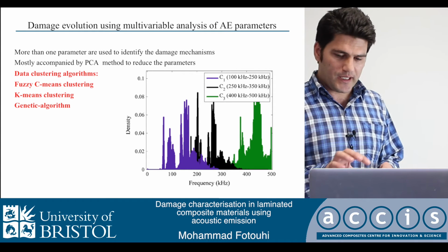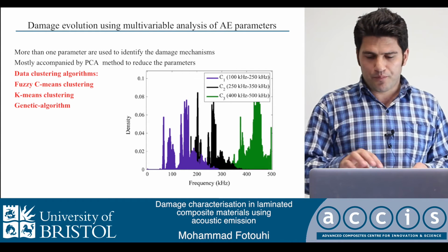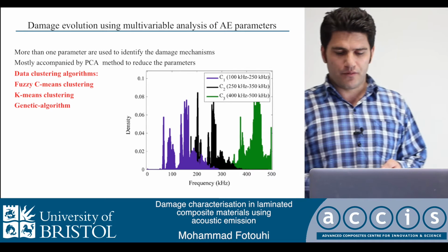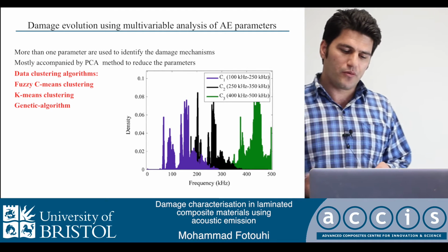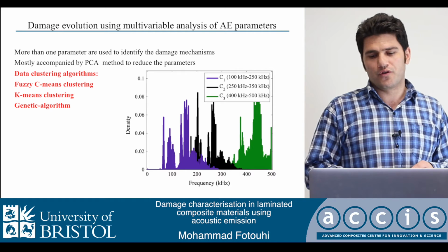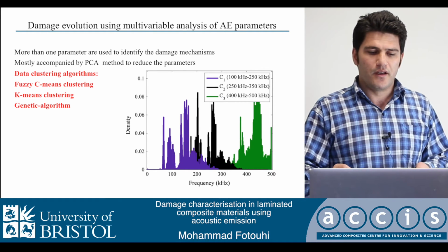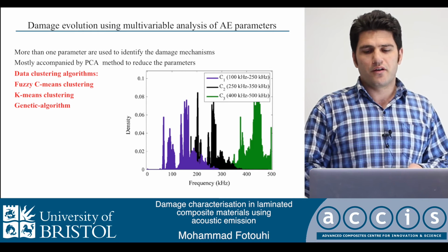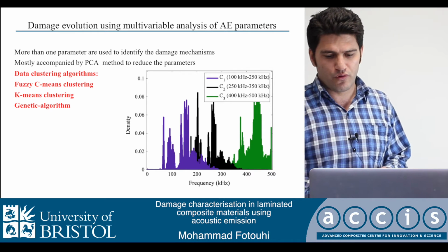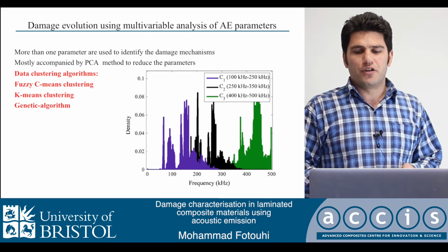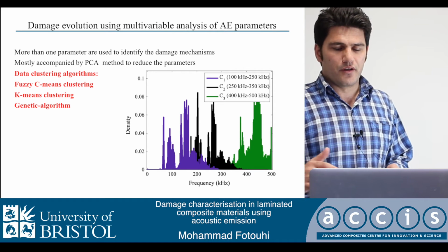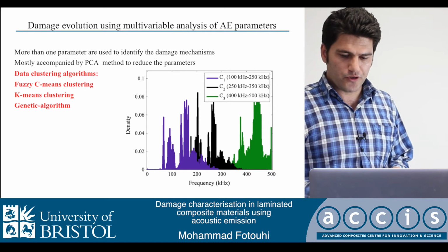We tried to classify the obtained signals based on the frequency content, and we found three different frequency contents. The lower frequency is related to matrix cracking, the middle one related to debonding and delamination, and the higher one related to fiber breakage.